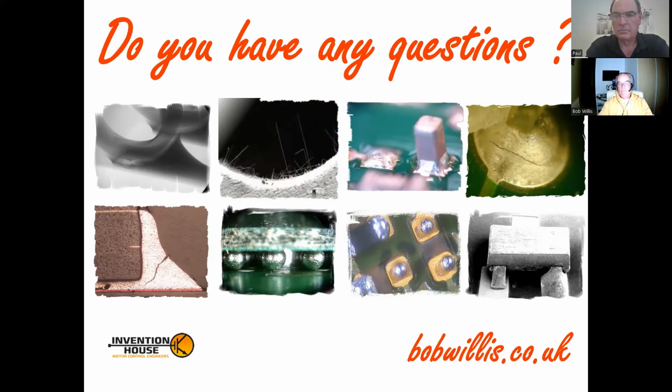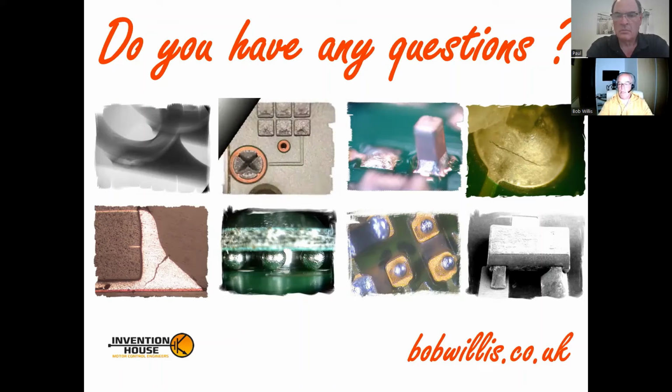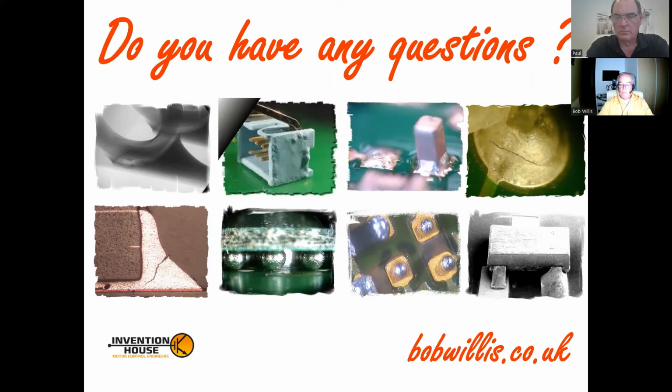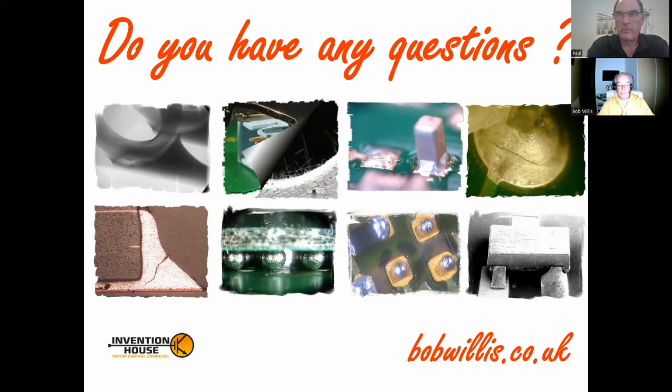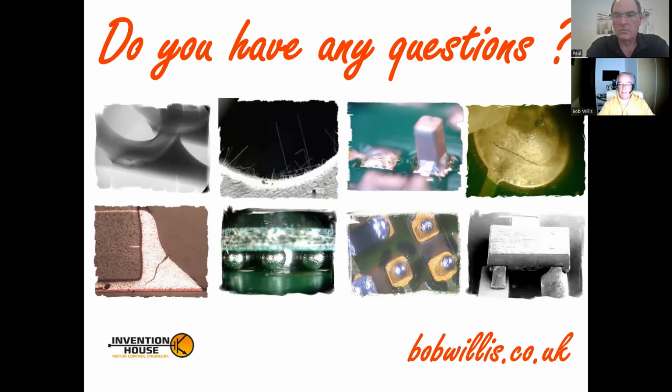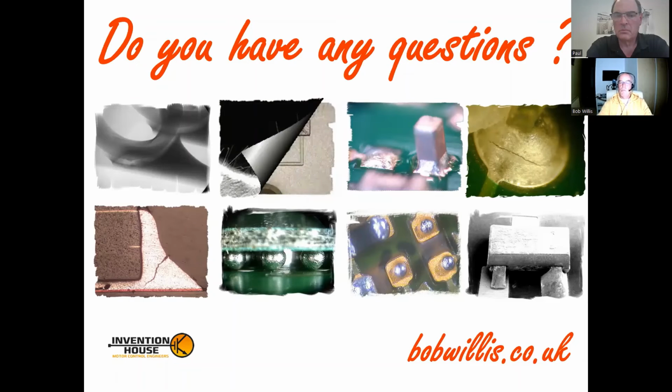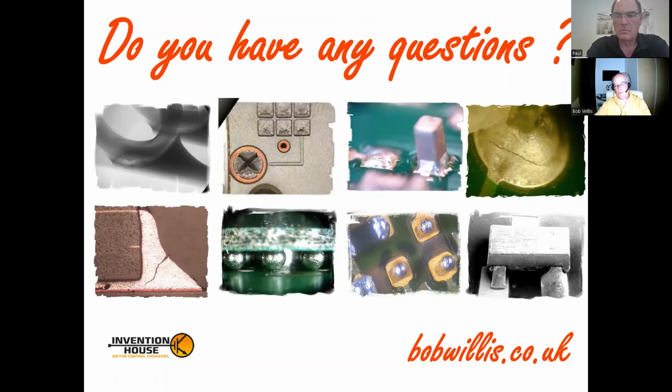In fact, it's more of a problem in terms of masking. If you mask a particular area you don't want coated with sticky tape, and that sticky tape isn't bonding to the surface, that parylene will get underneath there. So you've got to be more concerned about how well you protect the areas you don't want coated with that type of coating.